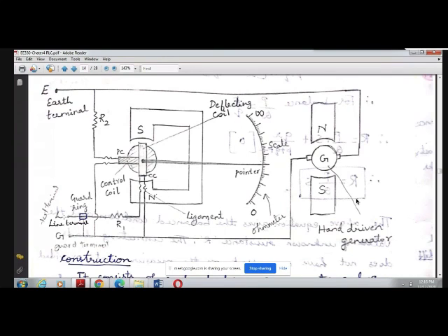So what is the resistance in case of open circuit? What is the value of the resistance in case of open circuit? Infinity. Okay, the resistance value is infinity. So now you are going to keep these test terminals open circuited, and you are going to rotate this generator handle. That is the hand driven DC generator, which has a handle, so you have to rotate it by using your hand, like manually you have to rotate it. You keep on rotating this.